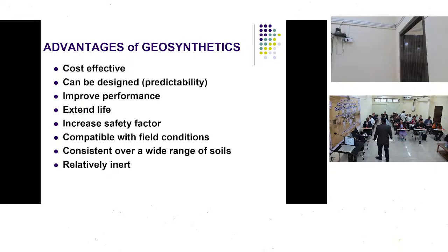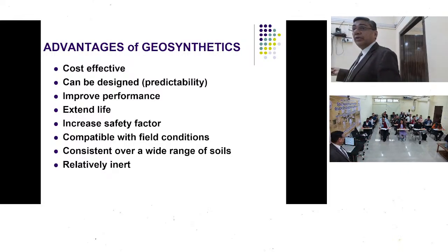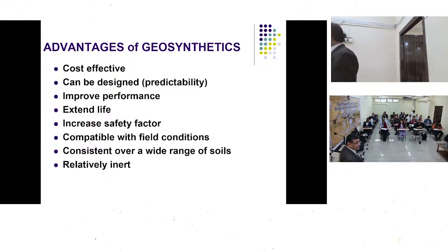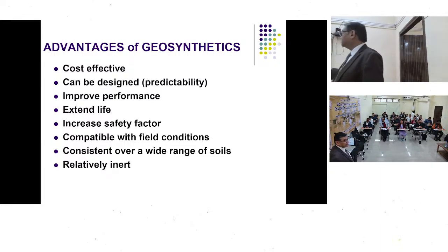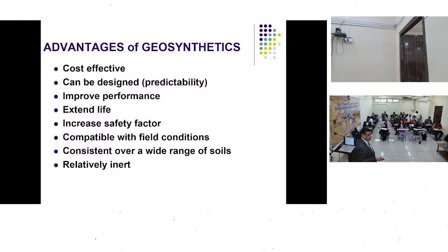It is cost effectively proven in our country, and that is why, if you see, in many of the tenders they are putting the usage of geotextiles nowadays. Obviously, it improves performance. It extends the life. It increases the safety factor if you are going for reinforced earth. It is compatible with field conditions, consistent over a wide range of soils, and relatively inert. So these are all the good things about geosynthetics.